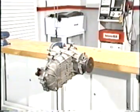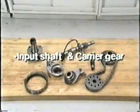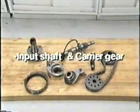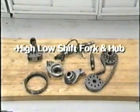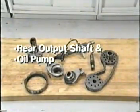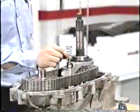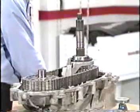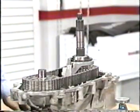In a manual shift transfer case, such as the Borg-Warner 1356 from a Bronco or F-Series truck, the major operating components are the input shaft and carrier gear, the lock-up shift fork, the drive sprockets and chain, the high-low shift fork and hub, the front output shaft, and the rear output shaft and oil pump. To direct the transmission's output to the front and rear wheels, the transfer case uses a front and rear output shaft. Both have sprocket gears linked by a Morse chain.